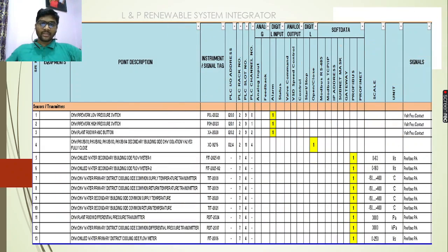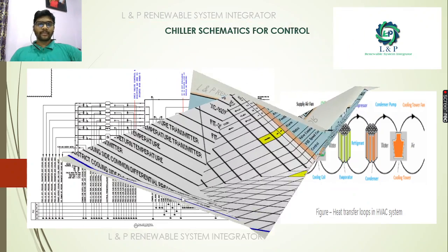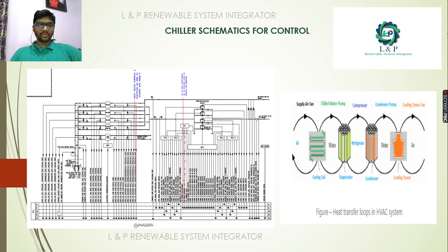As we told earlier, we are using so many sensors and pressure switches. Those are all digital signals we can monitor. Even the flow transmitters, supply temperature sensors, and pressure transmitters, through Profibus we can monitor all the parameters. This is one of the schematics showing how it is connected with the digital inputs, digital outputs, analog outputs, and communication signals with the PLCs.